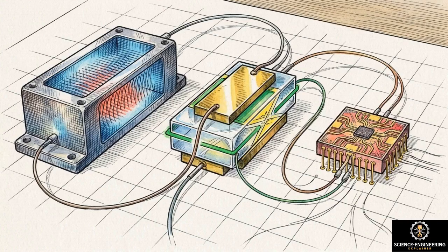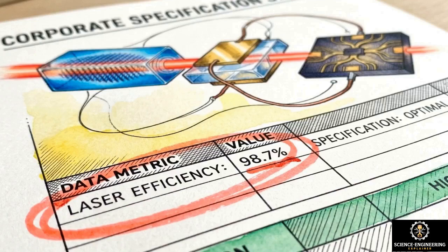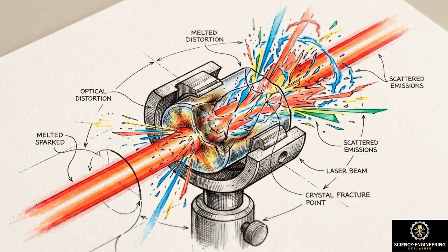We solve these challenges by mapping three distinct technologies, Acousto-Optic, Electro-Optic, and hybrid switches, directly to the scenarios they were engineered for. Prioritizing speed on a spec sheet while ignoring physical constraints, like beam aperture or baseline noise, leads to severe signal distortion and high hardware costs.